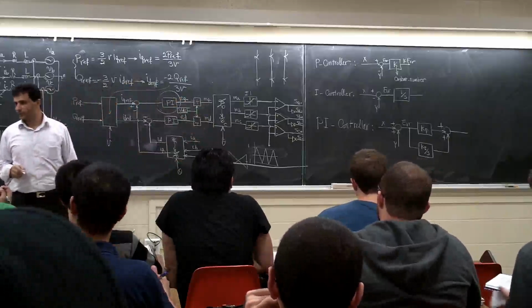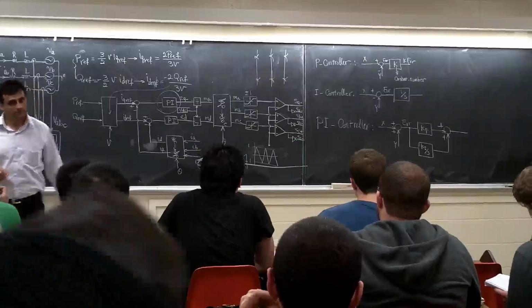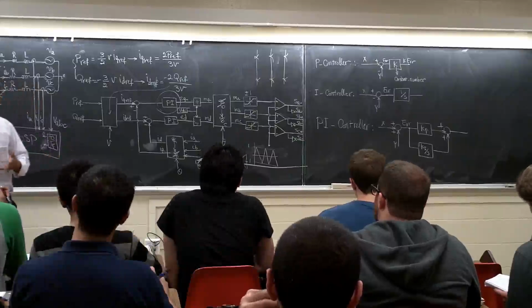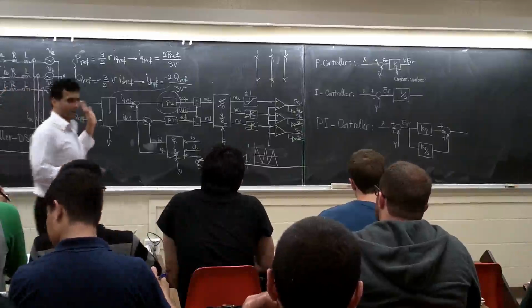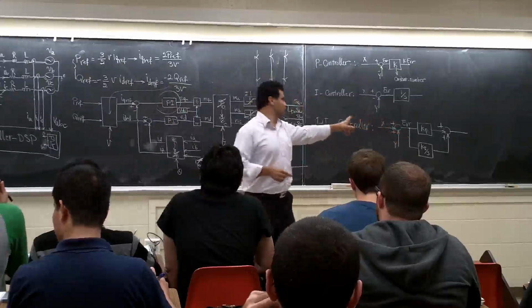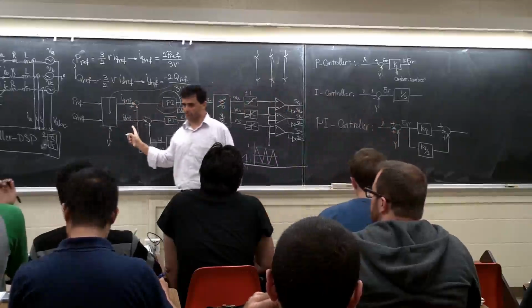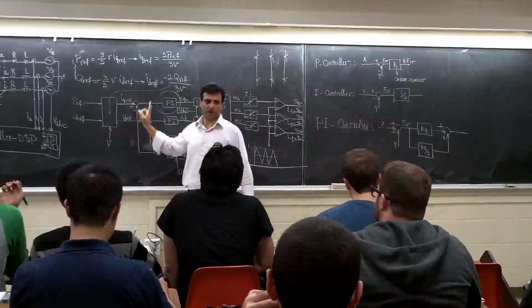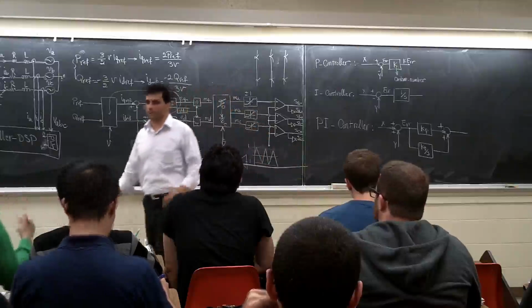Right? Clear? What does that represent? Like that adding it together? You build it in. Now if you use PCM, you have the PI already built in. You can use it. But at my time when I was doing my master's degree, we wrote all the C code and we do this one. You subtract this one from this one, for example here. You subtract this one from this one, right? Time it by Kp, time it by Ki over S, and add them together. This is my PI. I did my PI on myself.